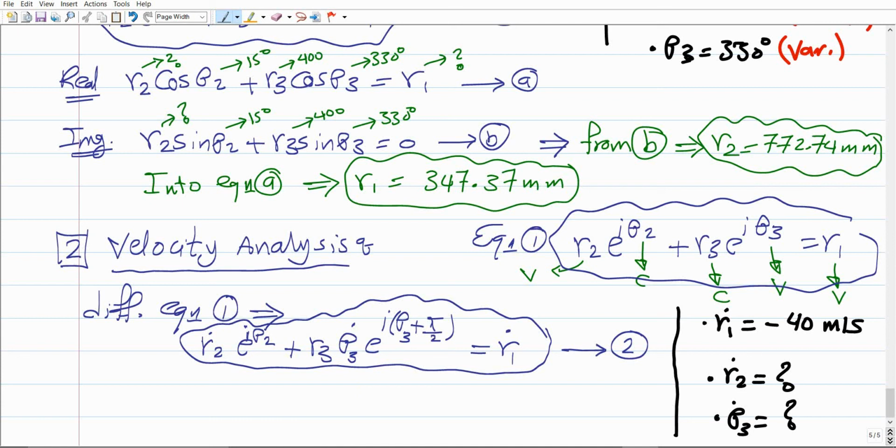It is typically the same as the position analysis, but in the position analysis we considered four cases. These four cases depended on the type of the unknown: is it direction or magnitude, and do the two unknowns belong to the same vector or different vectors? For the velocity and acceleration analysis, there are no cases.